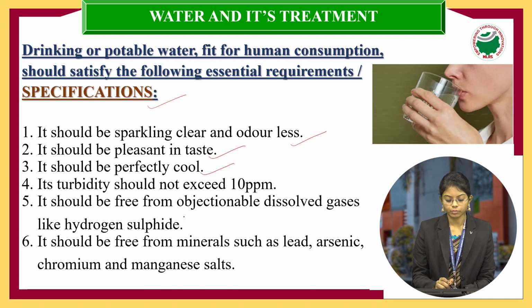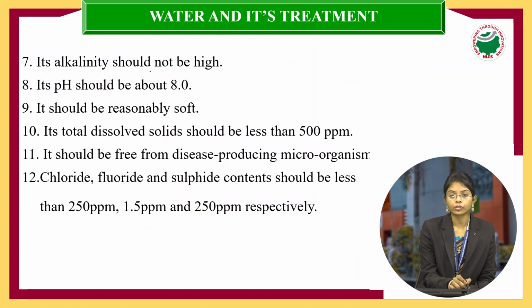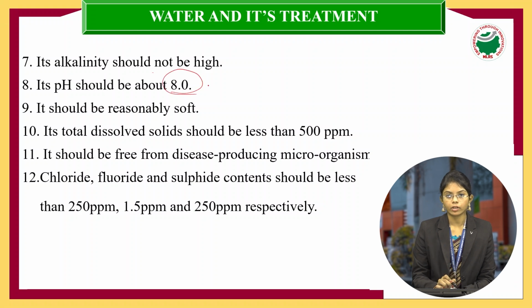It should be free from objectionable dissolved gases like hydrogen sulfide. One more specification is that it should be free from minerals such as lead, arsenic, chromium and manganese salts. Alkalinity should not be high, the pH should be 8.0, and it should be soft. These are the specifications.